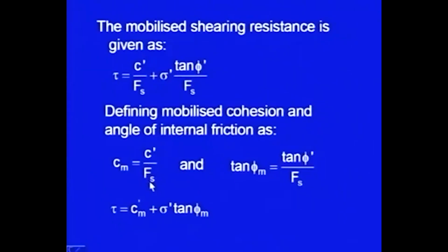What happens in the field is that factor of safety is basically used to have more confidence in the work. For example, we have measured the C dash value, and we have obtained the phi dash value also. So, if our confidence in C dash is small, then we should use a higher factor of safety.